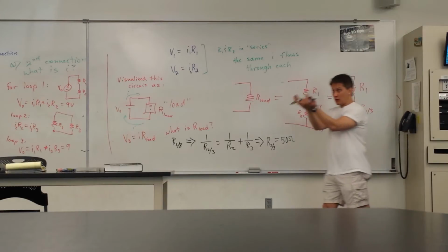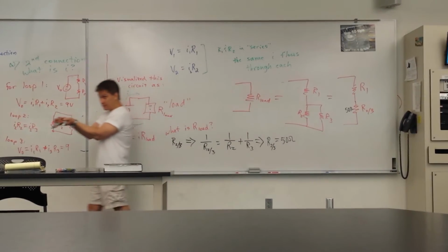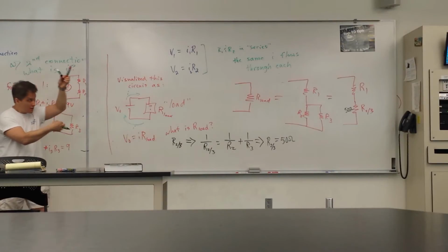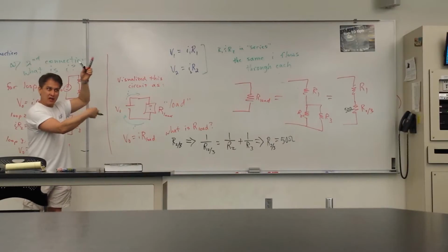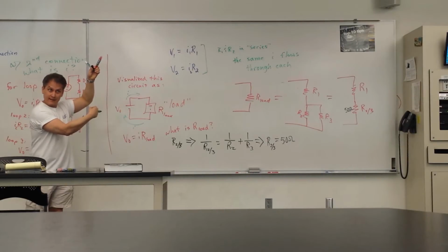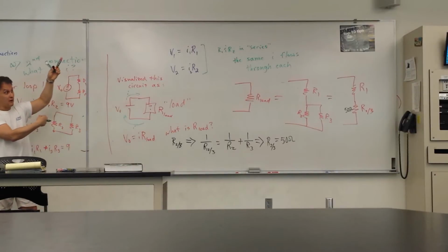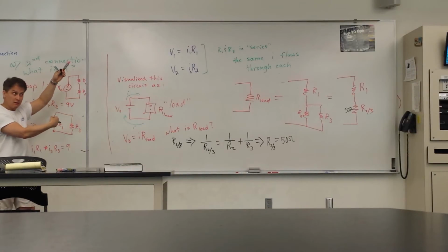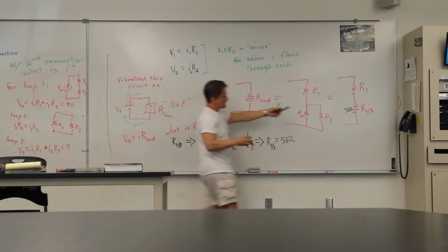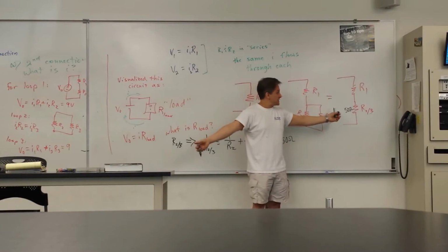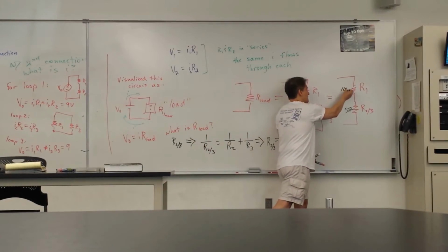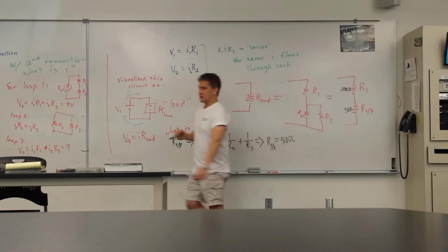this branch here, this combination, these two branches together in parallel, they're connected by V naught. Which, by the way, means that there are two elements that have the same identifiable potential difference across them. Same plus, same minus on either. That's another way of defining a parallel connection. Now we have a similar situation to what we had before. The only difference is it's a 50 ohm resistance combined with a 100 ohm resistance.